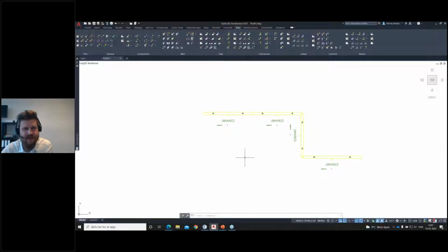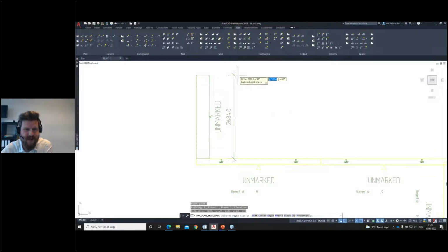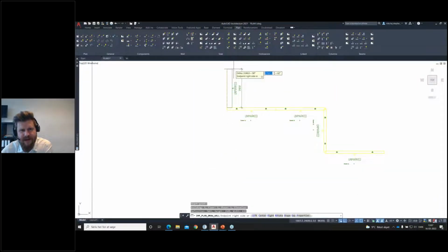Of course, here we drew some solid walls, and I might as well draw some sandwich panels as well. And as you can see here, for the sandwich panel, I have the bracing side on the same side as the element side, which will be up in mold. Typically, that's because, in my case here, up in mold is the back panel of my sandwich wall, of course.